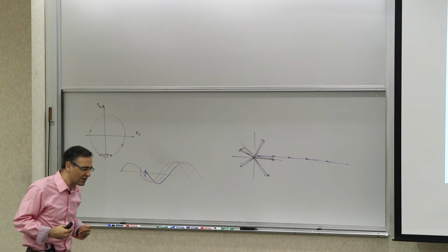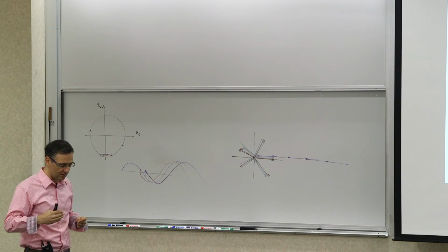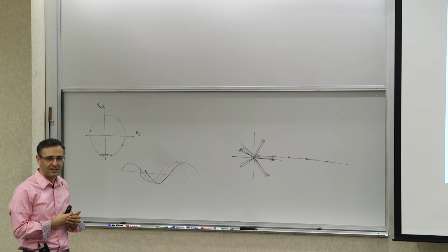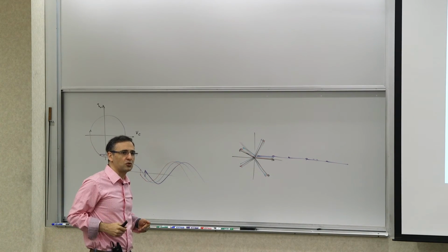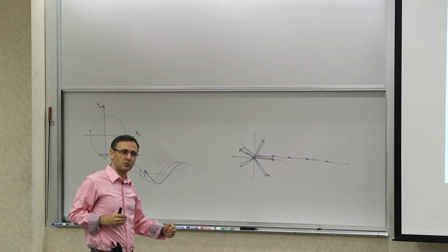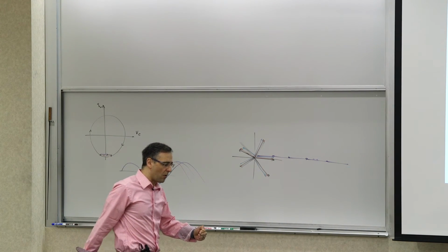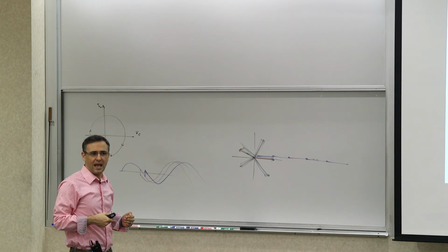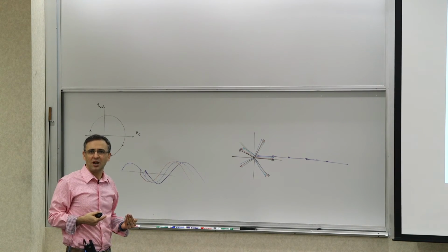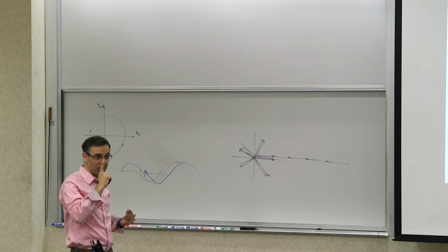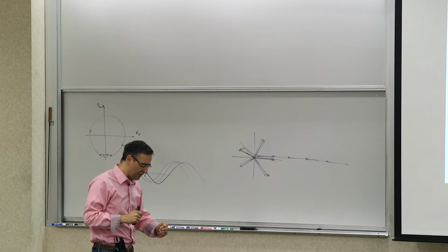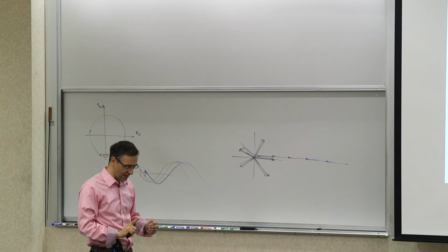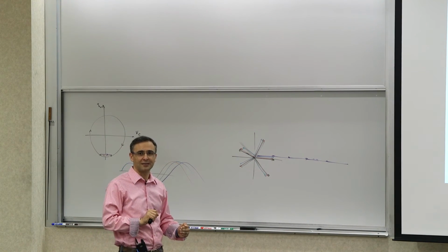So now what happens is that if an oscillator is running at a gigahertz or 10 gigahertz, the signal is transitioning, doing a full circle at 10 gigahertz. Now, I go through one device and it introduces some flicker noise shift. Flicker noise produces a little bit of a time shift. Now, I go through 5 stages and come back, and the flicker noise hasn't changed that much. So this is another way to think about it. If I have a rising edge going through a 5-stage ring oscillator, it shifts me forward a little bit.